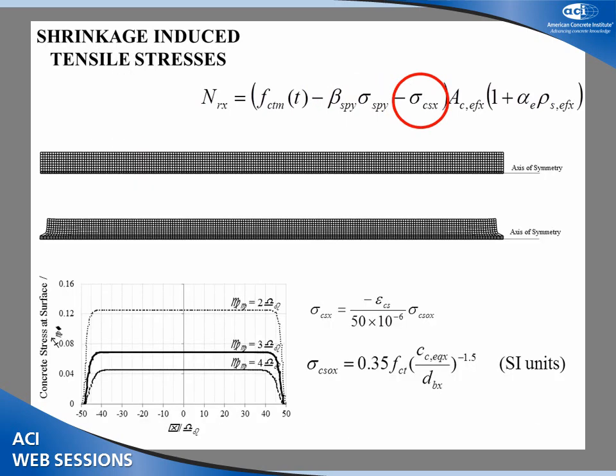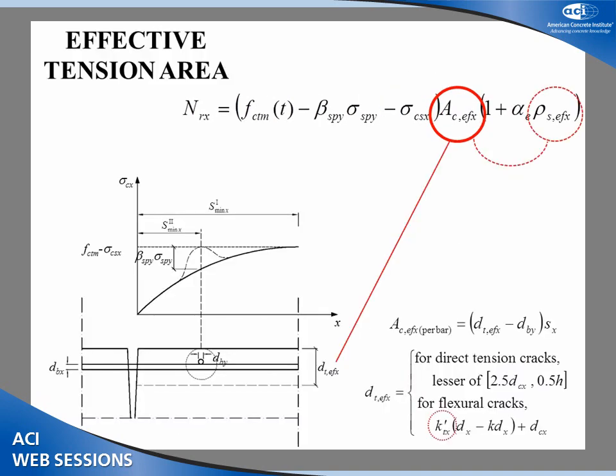The next thing is shrinkage stress. Obviously, when concrete wants to shrink, the rebar does not allow the concrete to shrink, so tensile stresses will develop in the concrete, and again, finite elements give us an idea of how much this stress is, to be used in this equation.